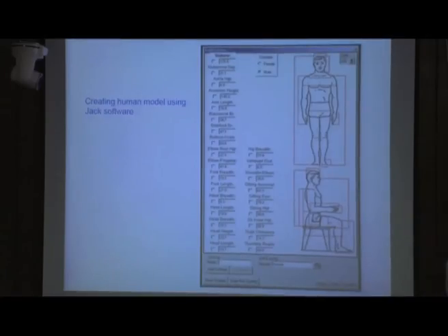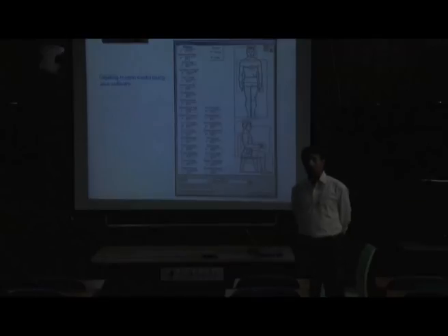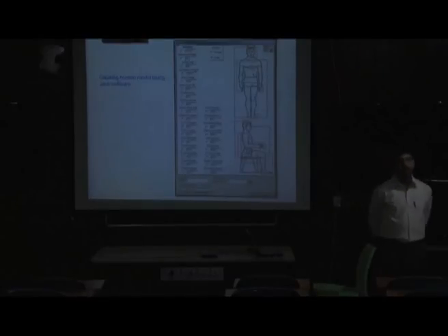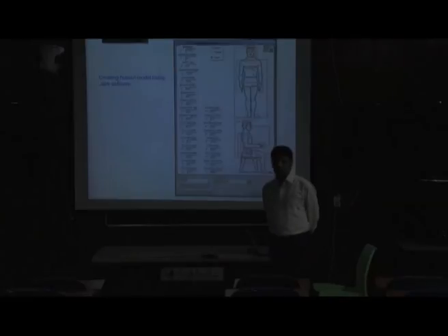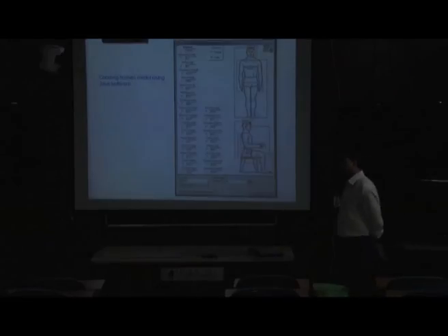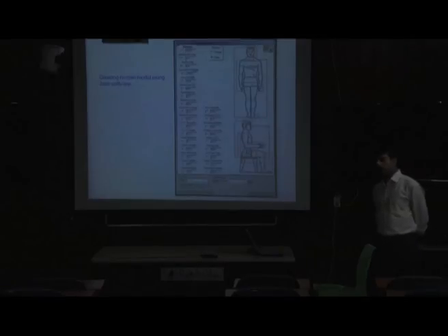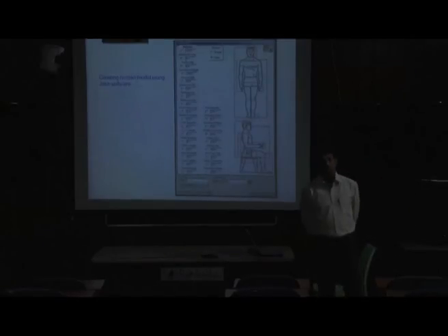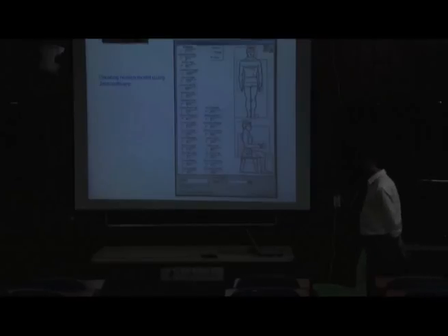So in this way, using different types of digital human modeling software, here we only discussed the examples of CATIA and JACK, but we can use any other software like Ramsis, SAMMIE, Santos. With this type of software, we can create a digital human model based on our anthropometric data. Further, we can manipulate biomechanical data also. In all these digital human models, there are options for modifying the joint limit, meaning range of movement modification. There is a provision for defining the comfort joint angle for different body joints. Based on that, we can also modify biomechanical data for that particular human model.